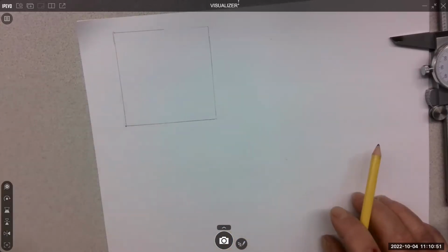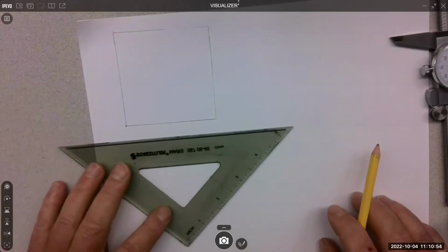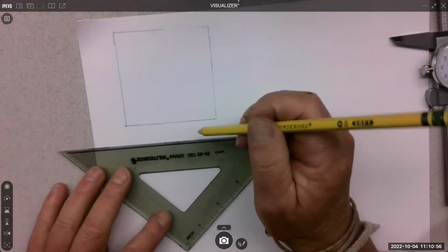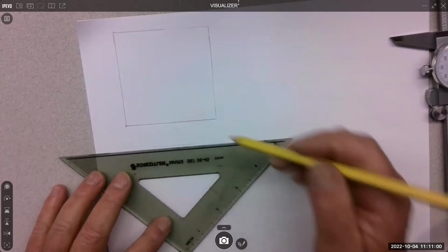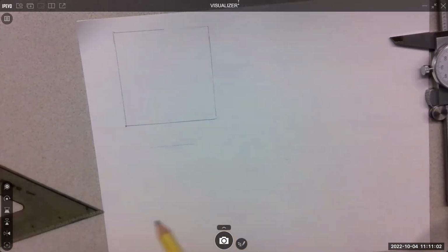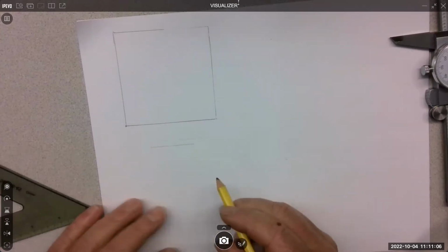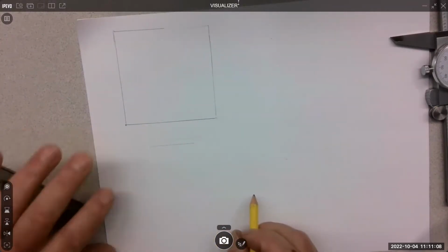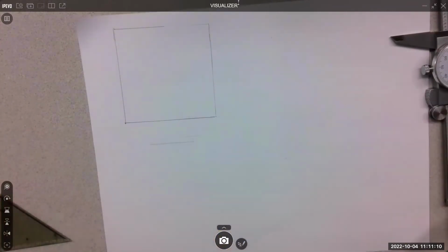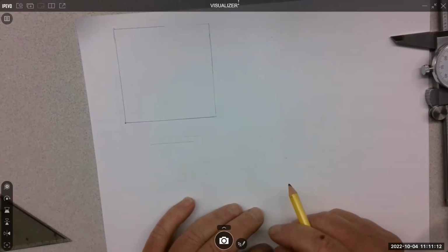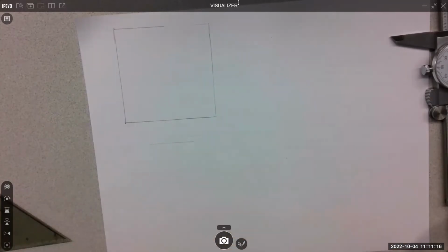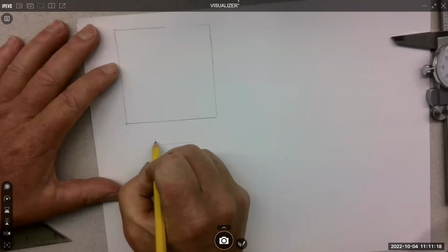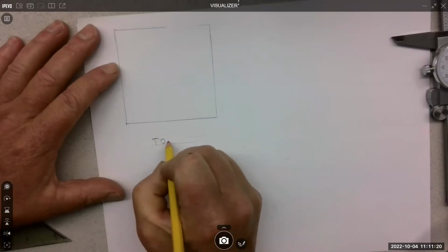Then, just to show you drawing layout, you're going to want a title. And again, you're not going to want the title too close to your drawing, because dimensions would typically go in there. We're not mentioning that now, but at some point we will be, right? So then I give myself some guidelines and I should measure that. Whether that's an eighth or a three-eighths or a quarter or whatever I ask you to make it, that's what it would be. But then I'm going to use my lettering skills.